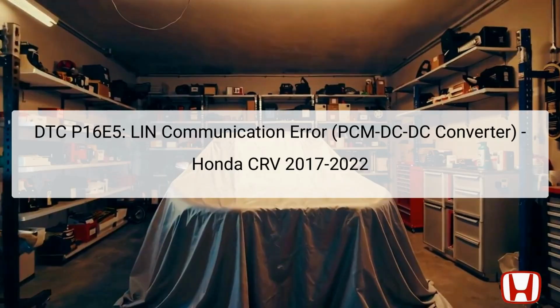The DTC P16E5 indicates a LIN, local interconnect network communication error related to the PCM, Powertrain Control Module, and DC-DC, direct current to direct current converter. This error may arise from intermittent electrical failures or disruptions in communication within the electrical system of the vehicle. The LIN communication network is crucial for enabling communication between various components of the vehicle's power management